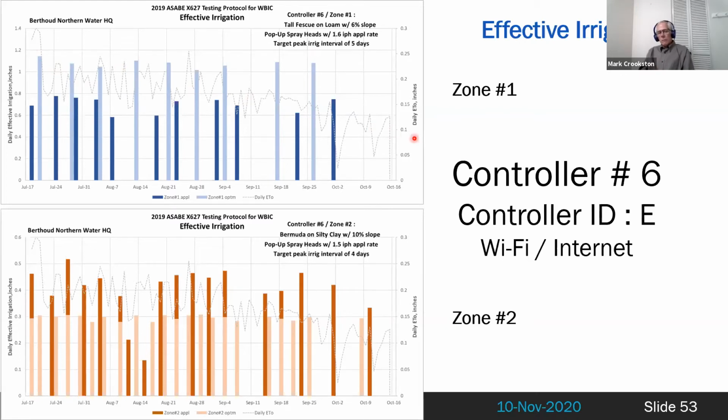And that's what the 90-day test is all about: we give the controller a changing weather requirement that it has to chase. And a 30-day test doesn't necessarily do that. So there you can see that by going from July 15th to mid-October, we got that seasonal drop in irrigation requirement. And you notice that this controller was watering more frequently, and then it started not watering as frequently. And that's exactly what we wanted to see.